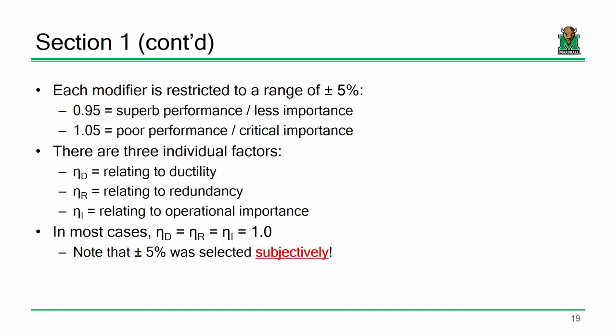The idea is that if that bridge or that element fails, the bridge is going in the river. Like, if I have a bridge that has 2 beams and one of those beams fails, you think that bridge can hold up? Probably not. It's going in the river, okay? So what do we do? We just erect bridges with 4 beams or 5 beams, and we don't have to worry about it. See what I mean?